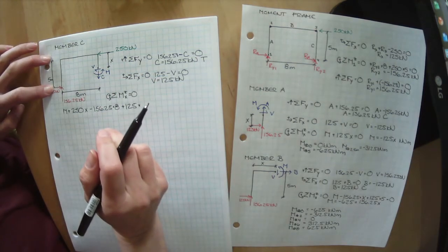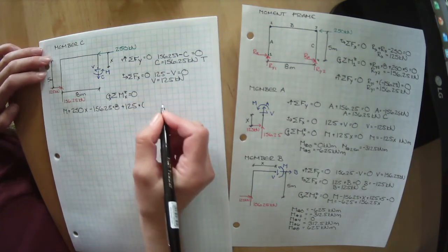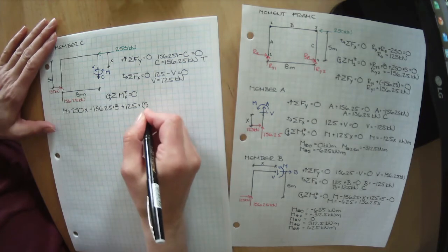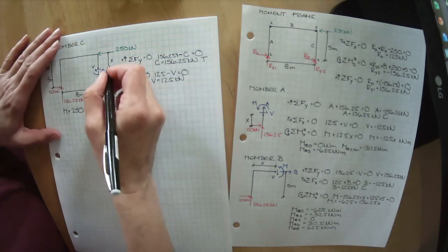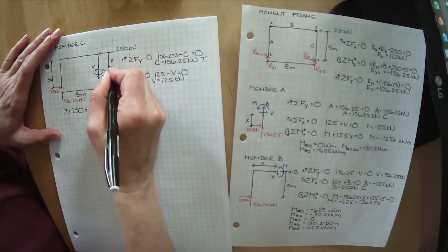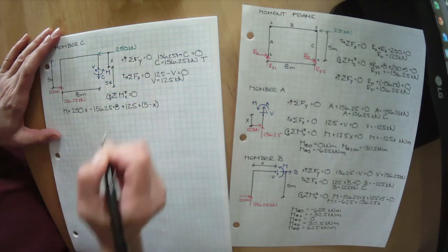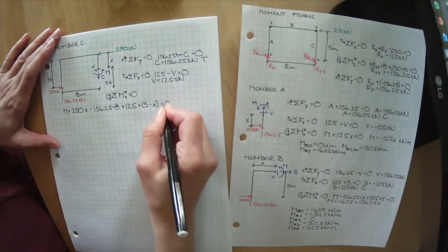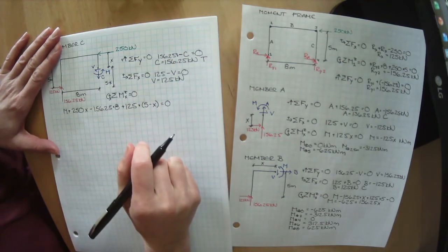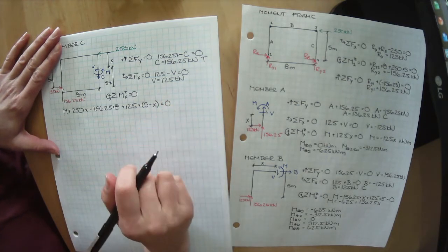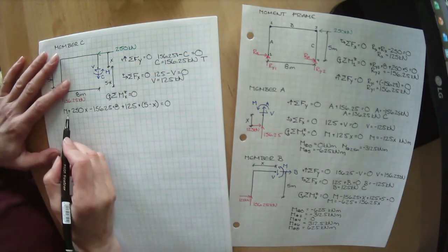This total distance is 5, and that is x. So that distance is actually 5 minus x. That's what that distance right there is. We could even fill that in if we wanted. And we want to know what it takes for the sum of all of these moments to make this thing not move. We want the sum of all of these to be 0. Okay, so we can start to work things out here.